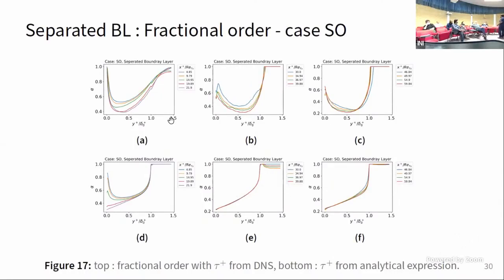But the terminology used in the turbulence community is eddy viscosity. If you do a little bit of algebra, you will find that it is of the same spirit as the Boussinesq equation, and that was the proposition of Prandtl, the simple mixing length model, and then the whole field of turbulence modeling has been focused on what that diffusivity constant is.